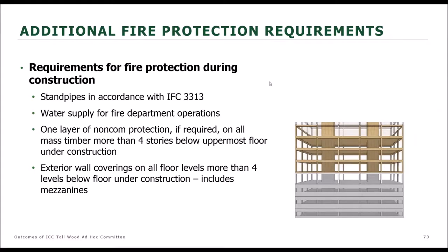How about during construction? Construction fires are a very serious matter. We do have a construction fire safety coalition. You can find that information on our website. For mass timber buildings, it will also be important. All the typical requirements for fire safety during construction in Chapter 33 of the IBC and the IFC will apply. Standpipes when the building reaches 40 feet, water supply for fire department operations, access to the site, even fire watches at the order of the fire official. It's not listed here. These will all kick in as is currently required.